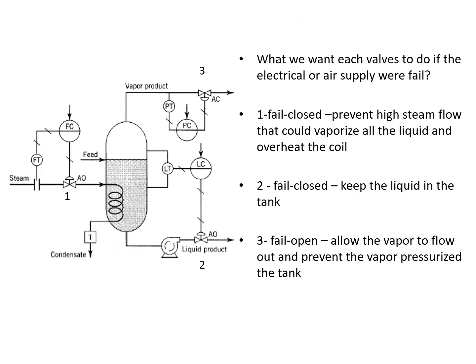Okay, so now we have one complete control system for the reactor. Basically, this reactor is installed with a heating coil, and the feed for this heating coil is steam. So we have a flow control system, a pressure control system, and also a level control system. Right now we will see, one by one, which type of valve is used for each control system.